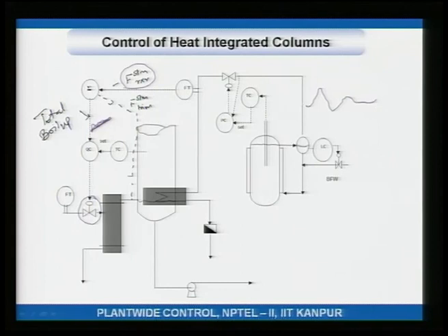So, there is variability in the steam being generated in the reaction section, but by adjusting the amount of steam in the trim cooler, I can quickly bring the total steam generated back to set point. As far as the temperature controller is seeing, or as far as this distillation column is seeing, the total amount of boil up remains relatively constant. Now, since the boil up is constant, nothing happens to this temperature.